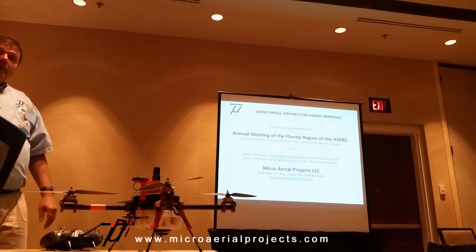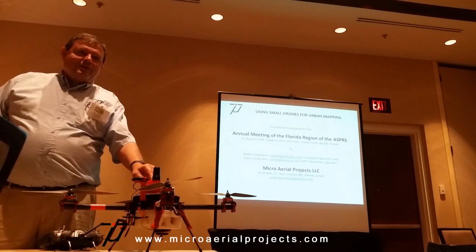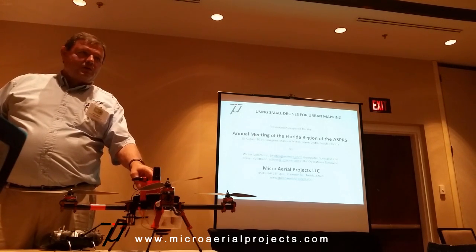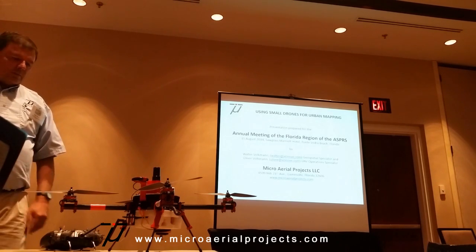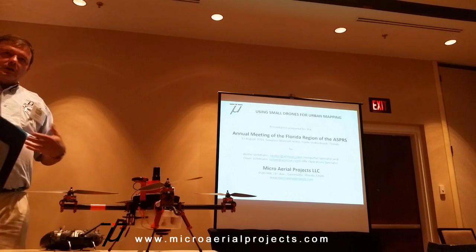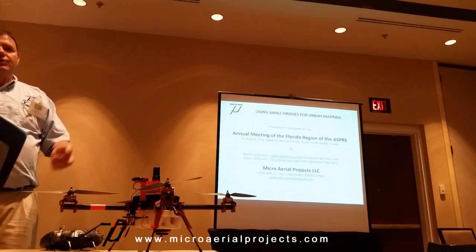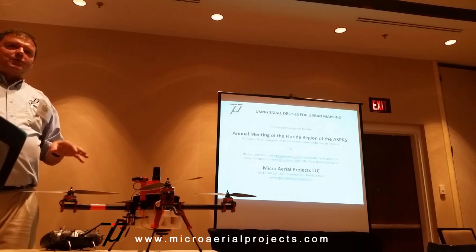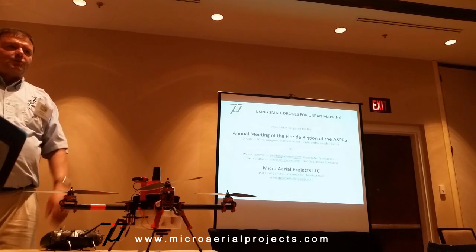What we did at the same time, but that wasn't part of the mission of our client, is we flew this with a dual frequency GPS receiver attached to the drone all the time. And it's linked to the drone, up to the camera. And so we recorded the event of each exposure, and we have this data now, and we're going to process it, and we're going to make some kind of an analysis on whether we couldn't perhaps get away completely without any ground control, just using airborne control.